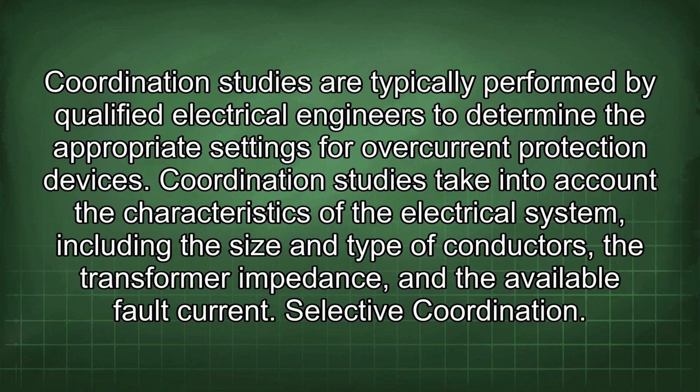Coordination studies are typically performed by qualified electrical engineers to determine the appropriate settings for overcurrent protection devices. Coordination studies take into account the characteristics of the electrical system, including the size and type of conductors, the transformer impedance, and the available fault current.